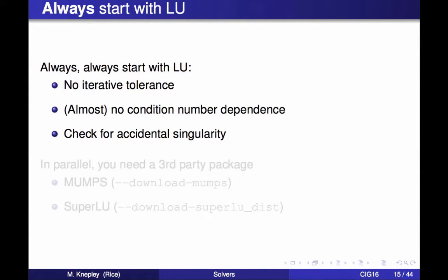So, when we are setting out to solve a problem, you should remember that taking someone's best effort, expert opinion for the solver settings is not what you should ever do. What you should do is solve it with a sledgehammer, okay? Take the slowest, most robust settings you have and solve it until you are absolutely certain that your physics is correct. Use coarser meshes, use simplifications, anything you have to do to check that it's right. And when it is completely right and you would like to solve a bigger problem, then and only then go away from the stuff that is guaranteed.